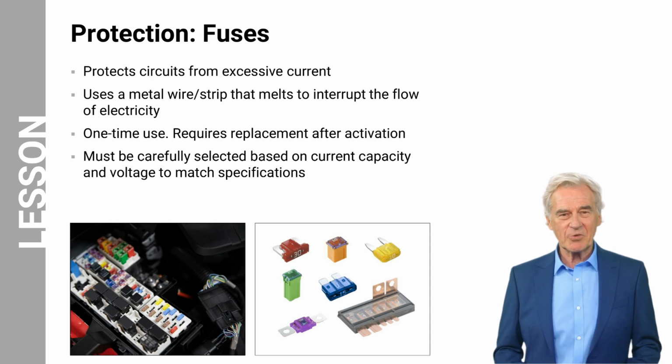functionality. The selection of fuses is a critical aspect of automotive electrical design, as they must be carefully chosen to match the specific current capacity and voltage requirements of the circuit they protect. Too low a rating may result in frequent and unnecessary fuse blowouts, while a rating too high may fail to adequately protect the circuit from overcurrent conditions.